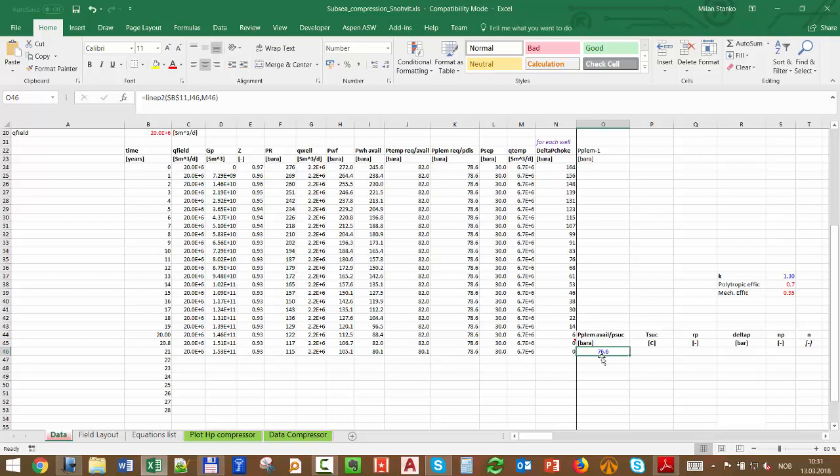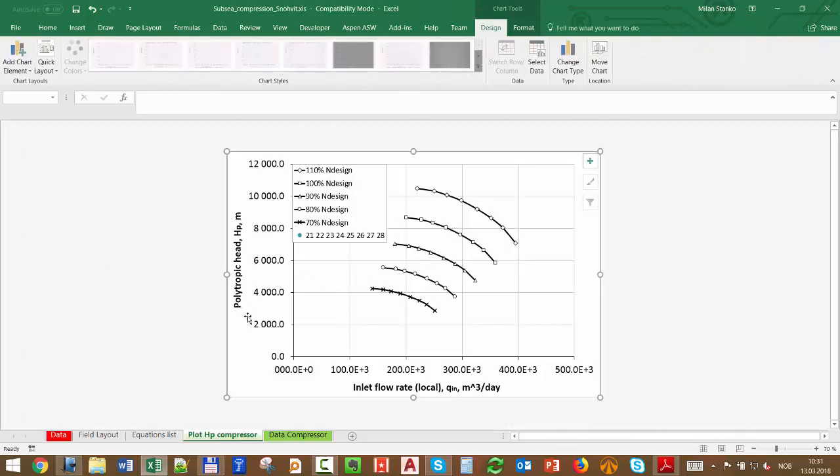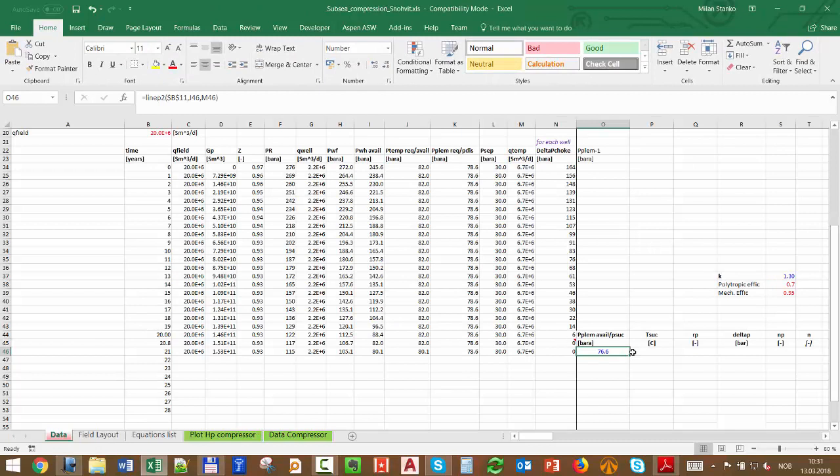We have already pressure ratio, right? We know that's important for a compressor. We know we have to be inside this map, and this thing called polytropic head, it has a pressure ratio inside. Okay, so that's going to give me the y-axis to see if it falls inside the map or not. So what else do we need that I told you is important?